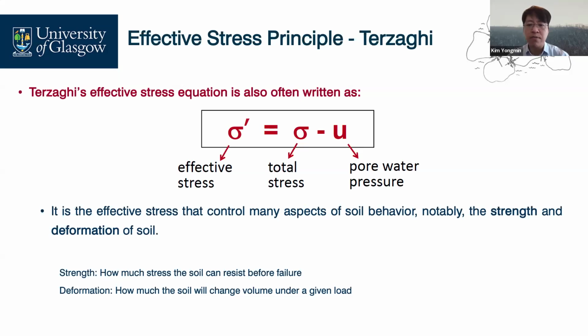It shows that all aspects of the mechanical behavior of saturated soils are entirely governed by the effective stress acting on the soil, because it represents the stress actually carried by the soil skeleton only. Sometimes the water in the soil, the pore water, supports certain loads. But we don't care about the pore water pressure because it cannot resist shear force.